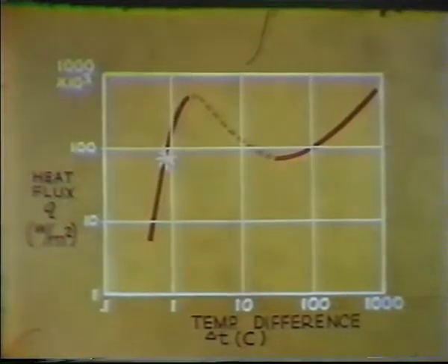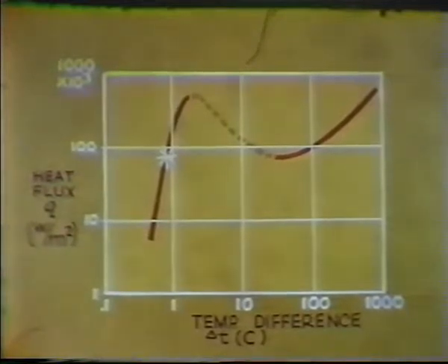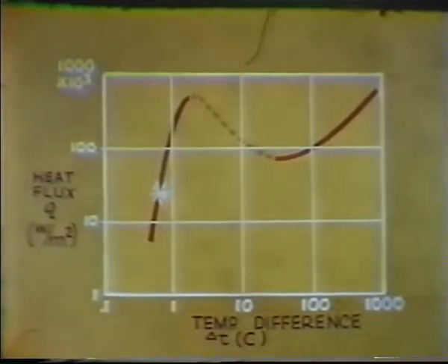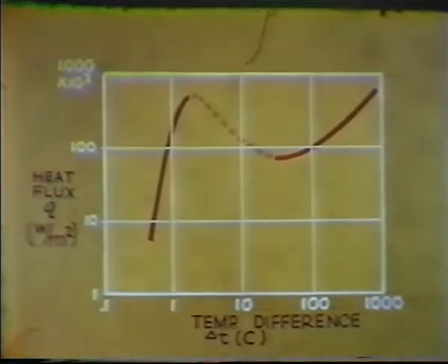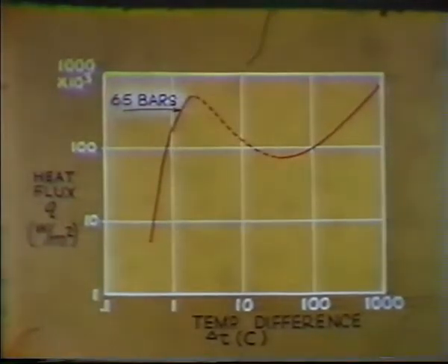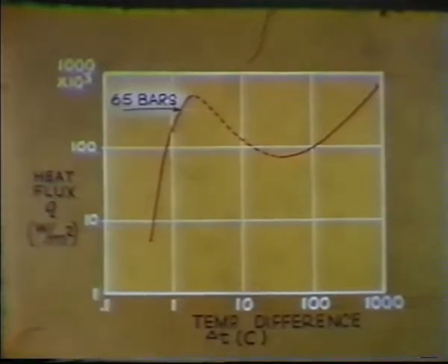Instead, film boiling persists below the burnout heat flux until eventually a sudden decrease in the wire temperature accompanies the return to nucleate boiling. The dashed portion of the curve is an unstable transition regime between nucleate and film boiling. This region could be investigated with an apparatus in which the temperature difference rather than the heat flux is controlled.